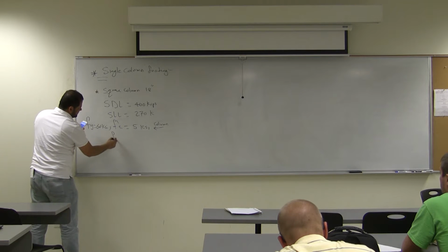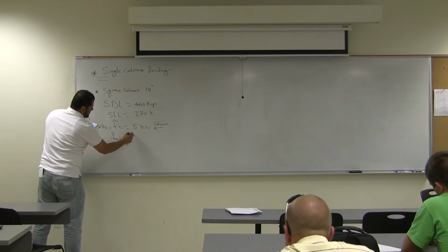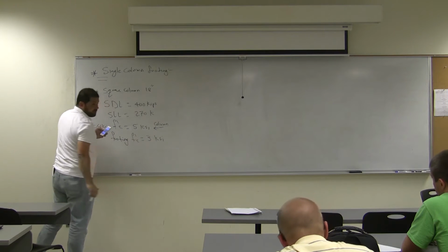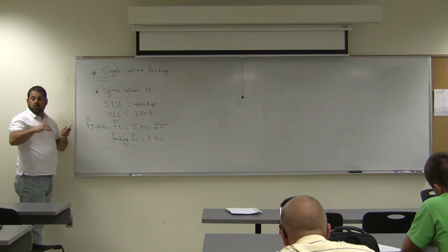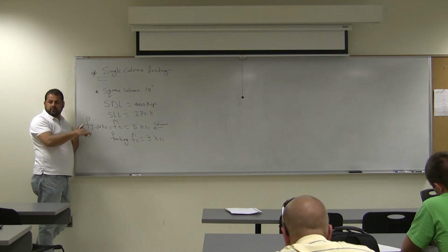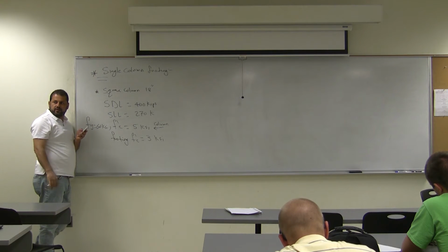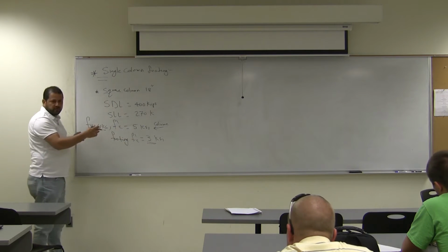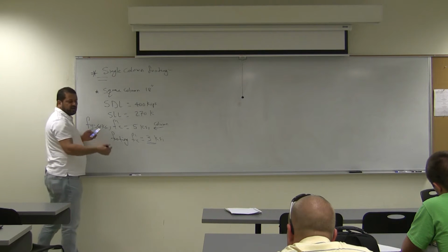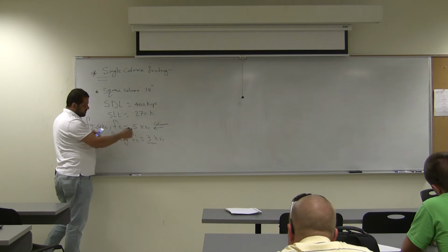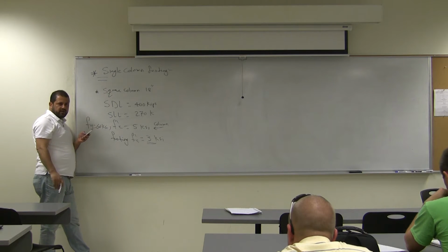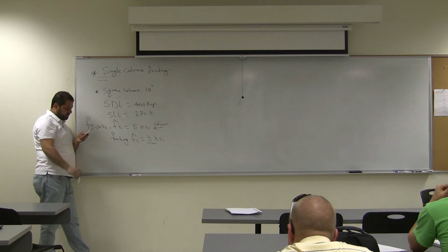For the footing, F prime C equal 3 KSI. By the way, it's common practice to use lower strength for the footing compared with the column concrete. So 3 KSI is the smallest concrete you may ever have, which is 21 megapascal. Usually it's easy now to achieve 4 KSI. Okay, this is just for the sake of this example. However, sometimes you may design a footing like that.